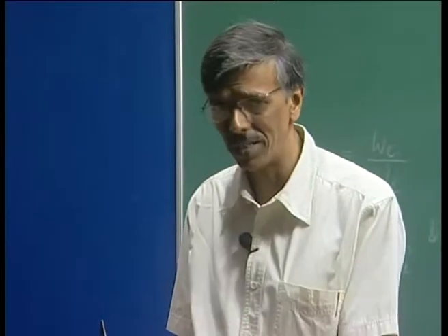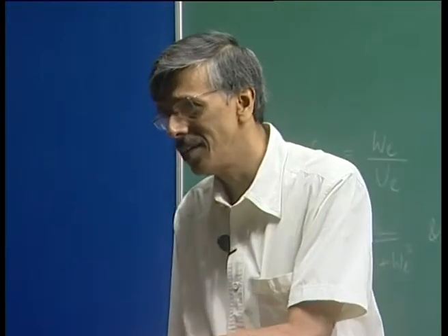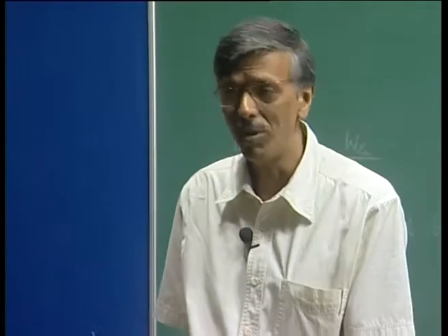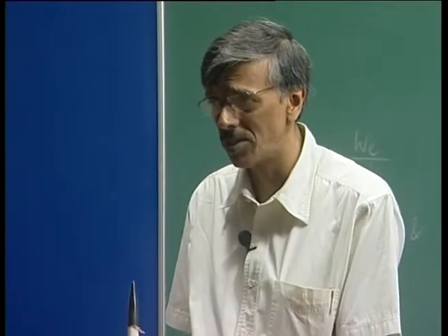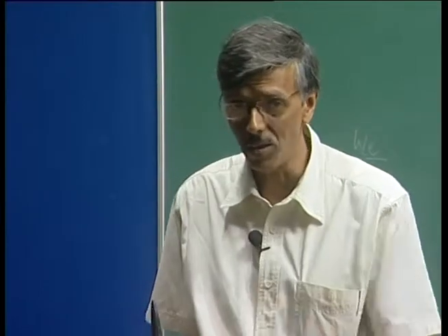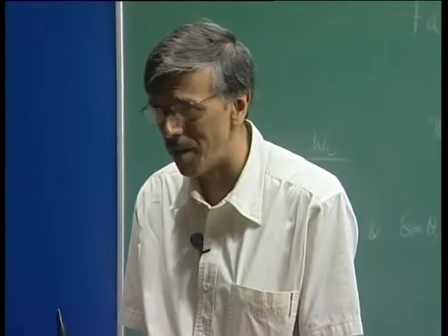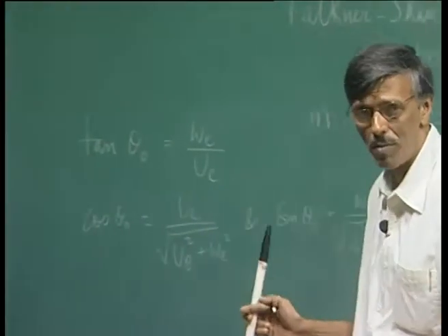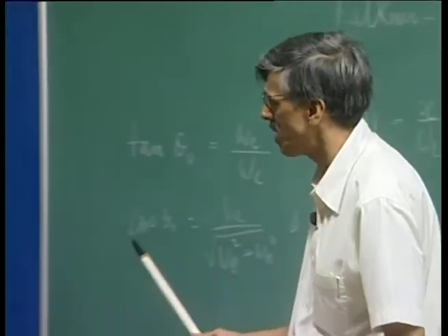It is much better than solving, let us say, the primitive variables and then converting those u and v components into vorticity. Because there, if I get a solution of a differential equation as u and v and then numerically differentiate to get omega, that accuracy will be compromised as compared to directly obtaining omega from a differential equation, right. So, that is what we like to emphasize.